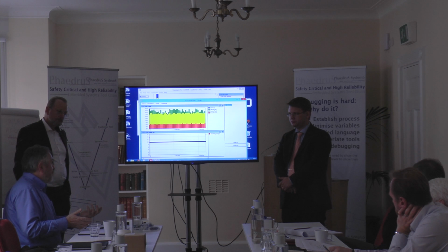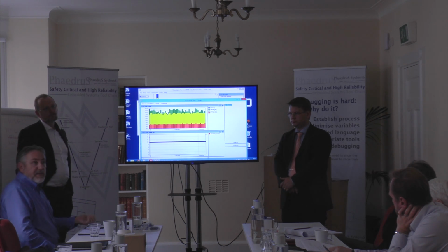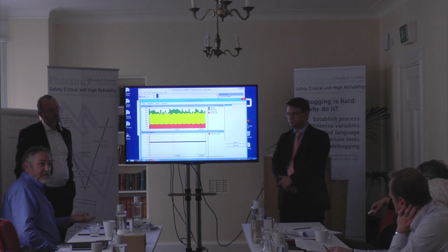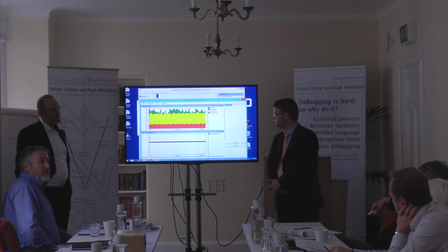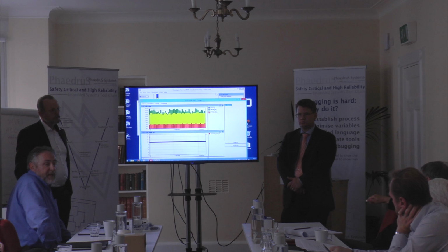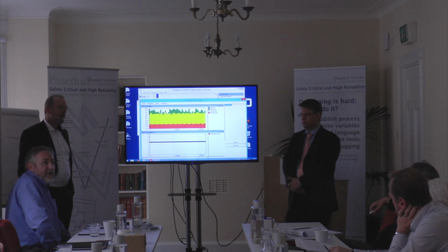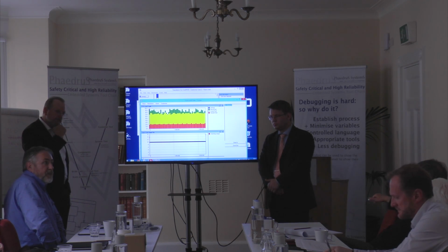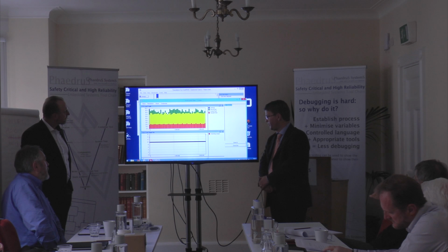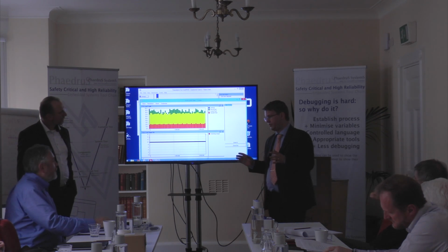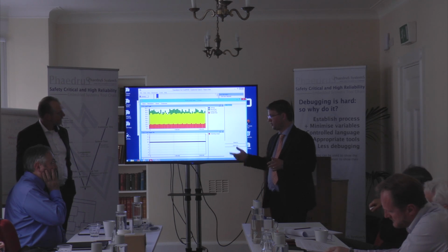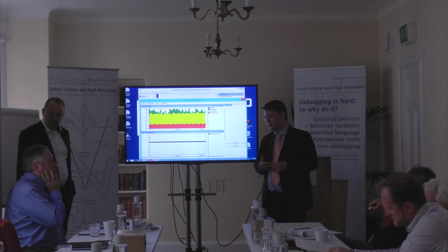The majority of Cortex and ARM parts don't actually have the trace module on them, and it is essential to have trace. So this lets you trace on almost every Cortex and ARM part there is with a standard JTAG, as opposed to having to have pins and the larger version of the chip with the trace module on it. And the streaming is actually not just for ARM. The JLink streaming supports the Renesas RX series as well.